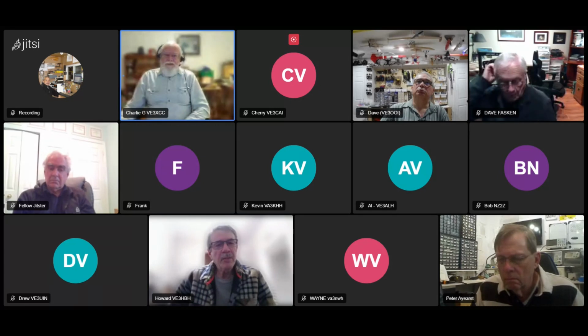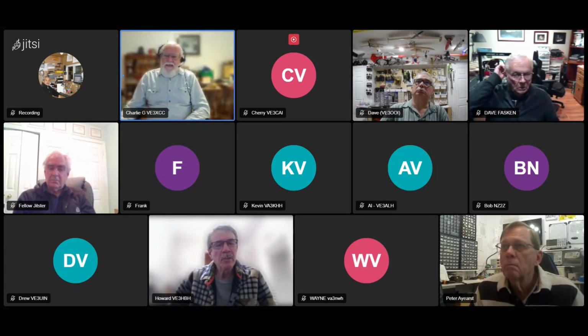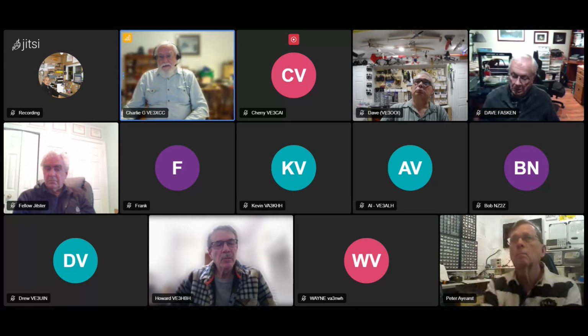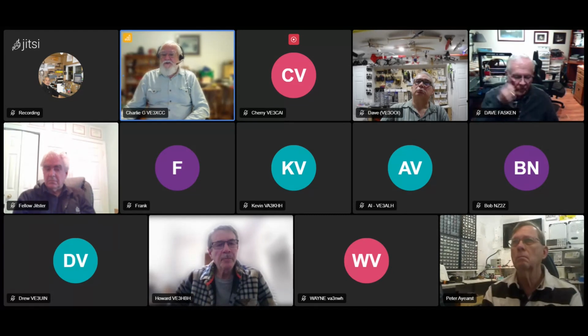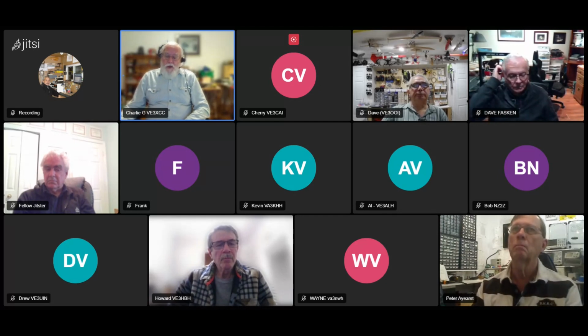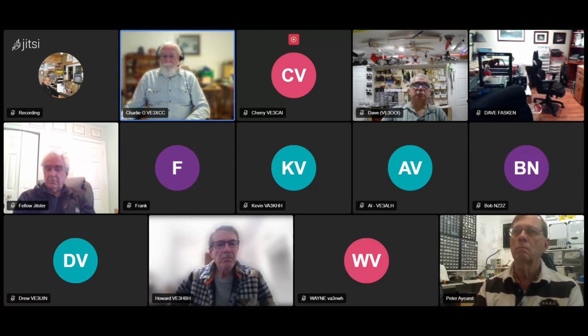So the typical NanoVNA that most of us own has about a 70 dB dynamic range. The latest and greatest V2 version, which I don't think any of us in this group own, is where you get into the 90 dB, and then there's the V2 Pro, which gets up to 96. So the quality is actually meeting or exceeding what you get with the $2,500 unit? It absolutely is. And it fits in your pocket. These are amazing little devices.